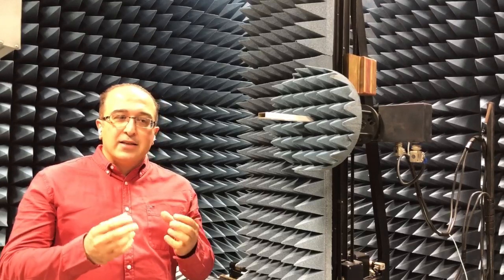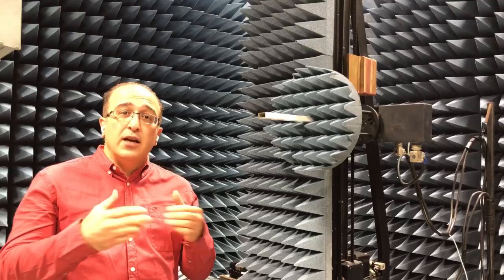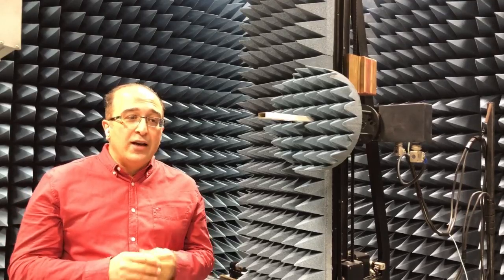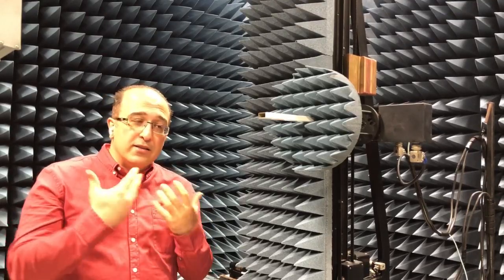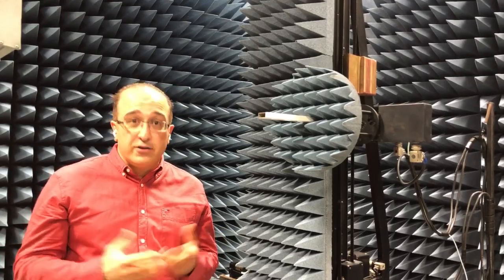So in the previous lecture, we talked about microstrip antenna, and we thought of microstrip antenna as essentially an aperture antenna. So we had two radiating slots on the two sides of the patch, and through that slot, this microstrip antenna will radiate. And it's an aperture antenna because we have a certain electric field distribution over the aperture of the antenna, and then through this electric field distribution we get to our desired radiation, in fact.